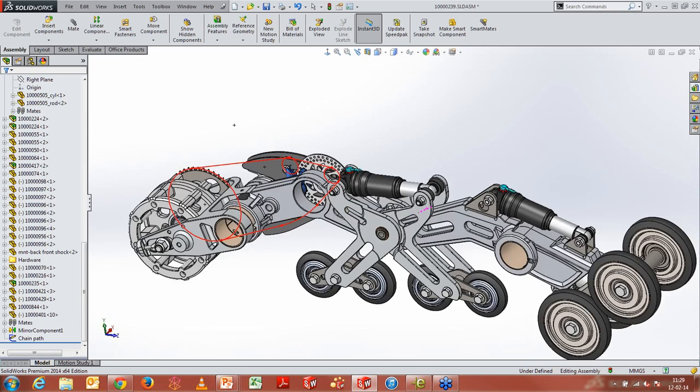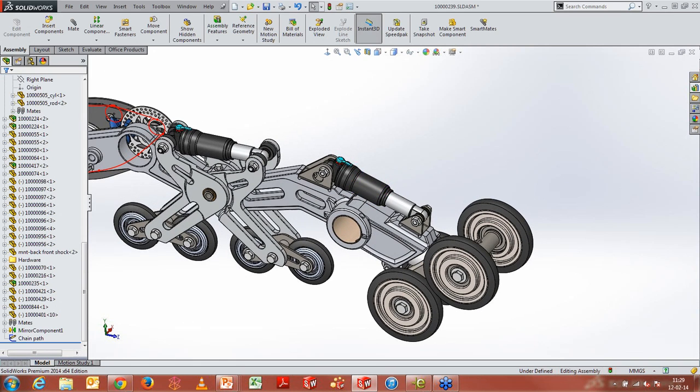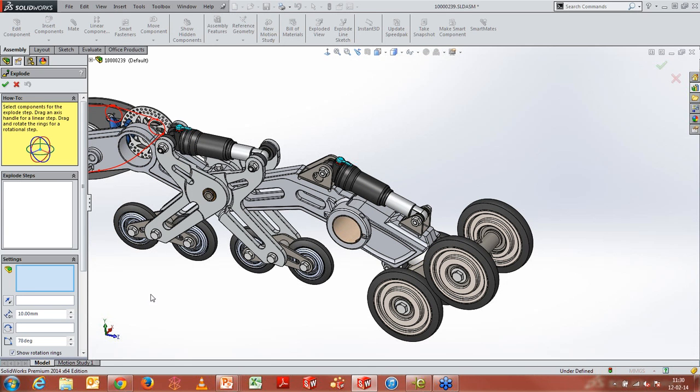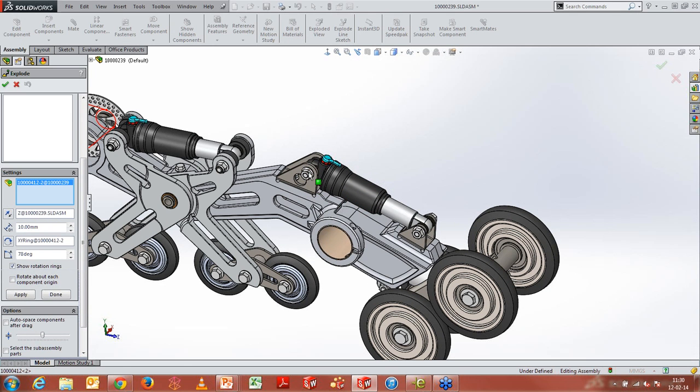Now, I was talking to you about the exploded view. So let's say, for example, I want to create an exploded view for this piston sub-assembly. All right, so I go to my explode view, I have this new option over here which says rotate. So what I do is, let's say for example, I take these nuts, I just drag them out. Similarly, I take the screws that I have, I drag them out as well.